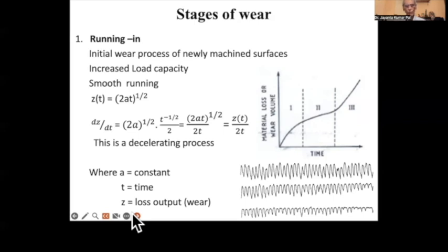The picture below shows that a rough surface becomes smoother and smoother, and eventually it becomes very smooth. But we should not allow the surface to be very smooth. If it does, then there is a possibility of seizure, and this we do not allow.